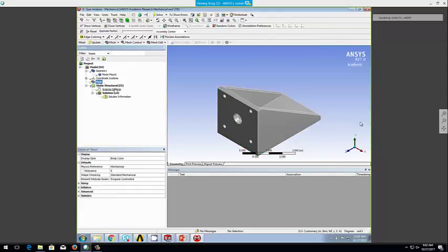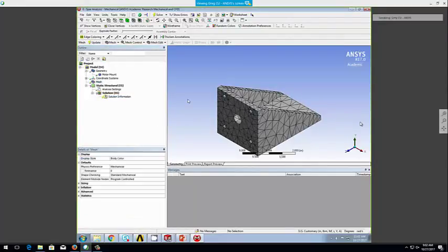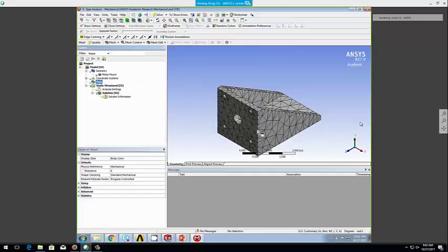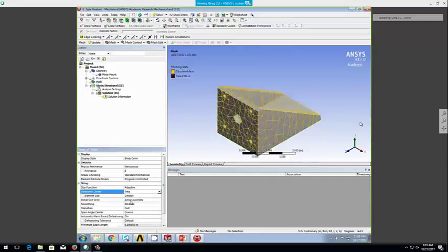Now this would be a limit, right? But you would say, the carbon fiber spar is the thing that is predominantly supporting the load, so we'll just model the carbon fiber spar. Things like assemblies begin to get really tricky. We had a student a couple years ago trying to simulate their plane, but the assembly went crazy and was never able to actually solve it. So these are types of things that you should think about. I'll show you a few more things here.